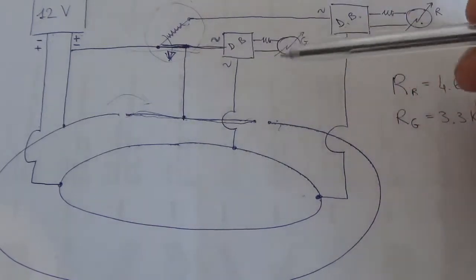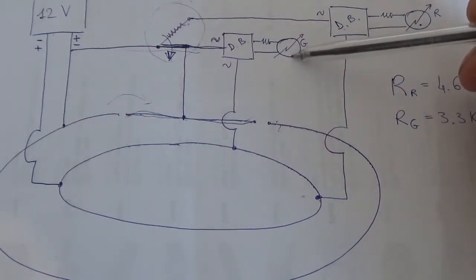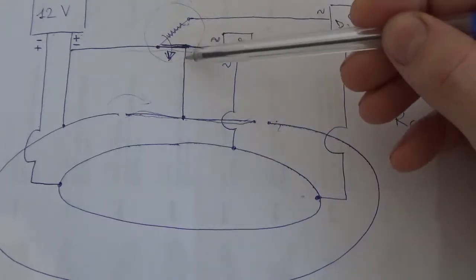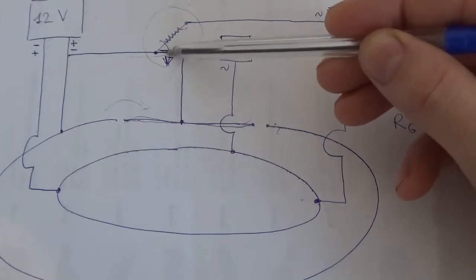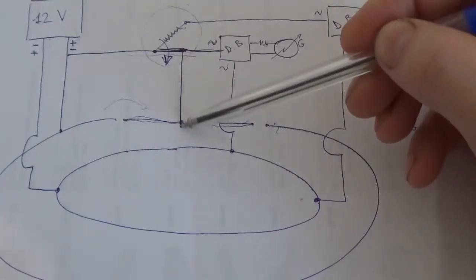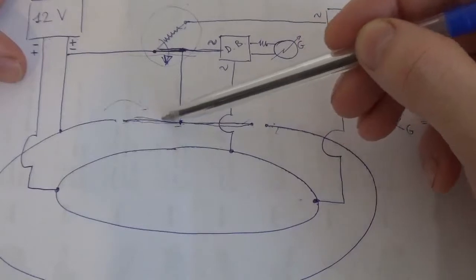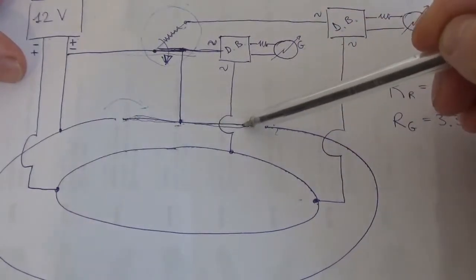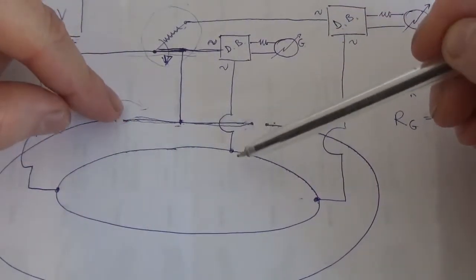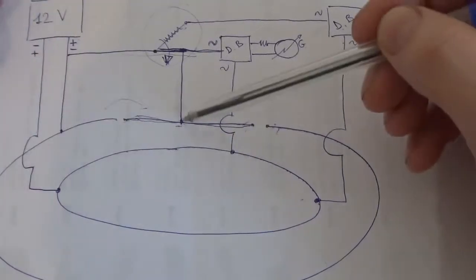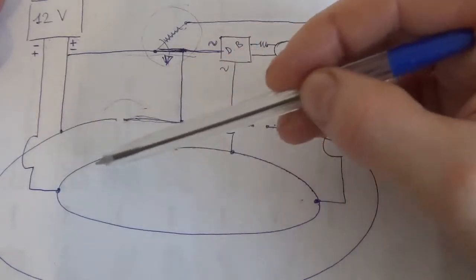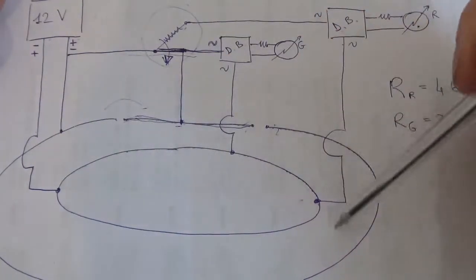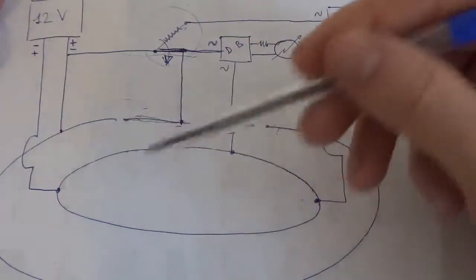At the same time the green LED is on, and due to the fact that the circuit is closed now, there's going to be tension over this section of the rail. Therefore there's going to be a difference in potential, because this is connected to the plus while this is connected to the minus, and the train is able to run all the way through without stopping.